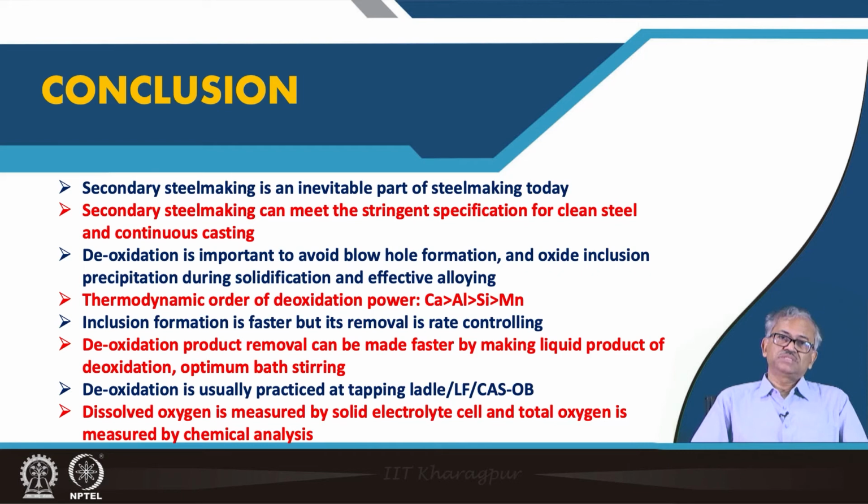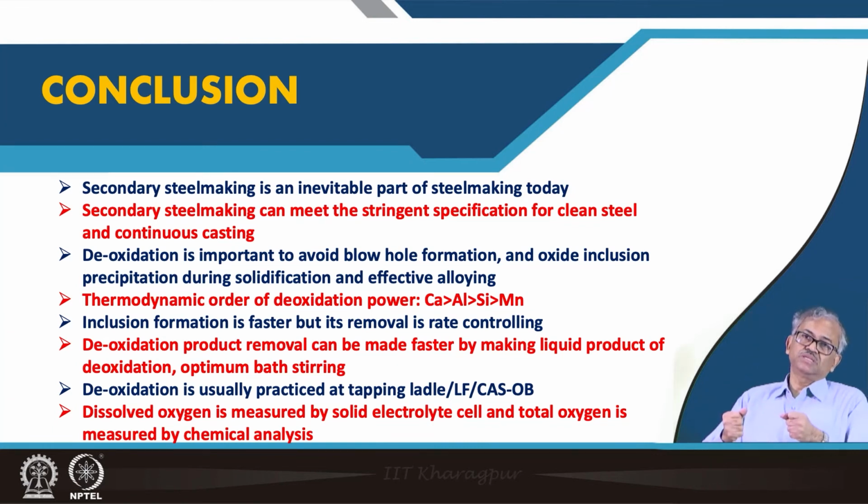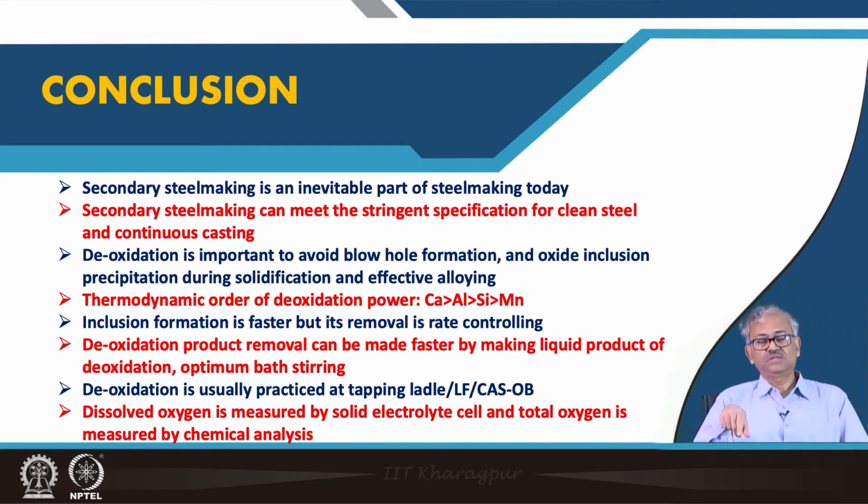But the problem is, as I said, calcium is not usually used as a deoxidizer for bulk deoxidation, because it is highly volatile and reactive. So its recovery into the bath is very less, unless you use some injection technique. Injection technique is important. You cannot dump the calcium on the slag, it will be totally wasted. You have to have some injection technique in place, either submerged lance injection or wire injection. Through wire injection, cored wire injection, you can add the calcium. Otherwise, you cannot simply dump it.